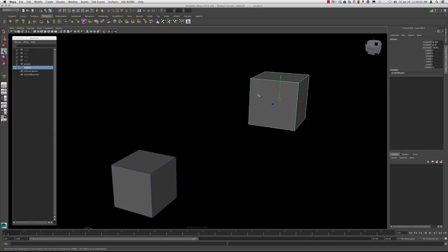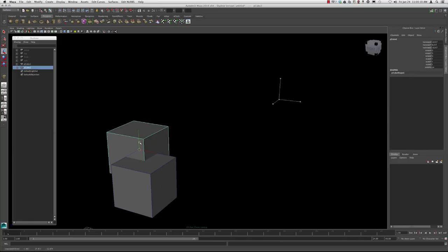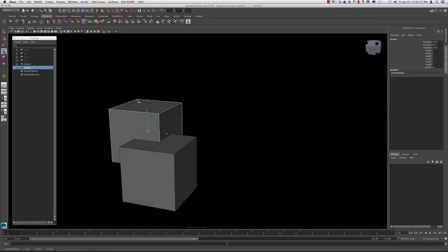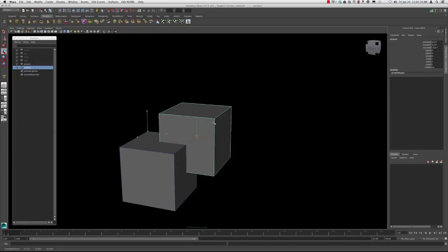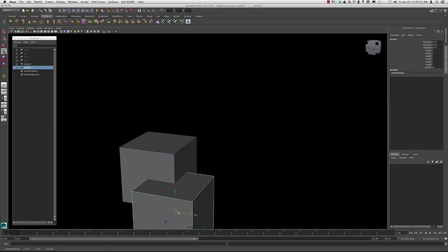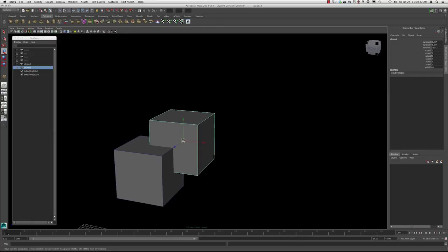So once that happens, if you just click and drag, then you'll notice that it'll jump from wherever it's at directly to the closest vertex where you pointed your mouse. And I'm not holding anything but the left mouse button, and you'll notice that it's snapping. It will only move to a vertex position. So, of course, now you can't get it out unless you turn your vertex snap off.